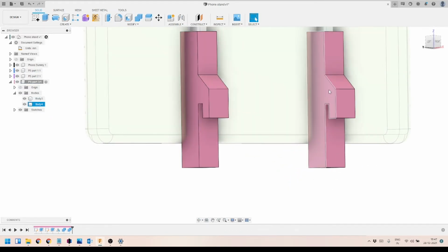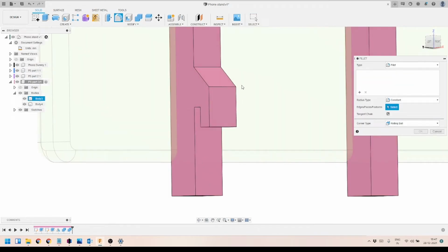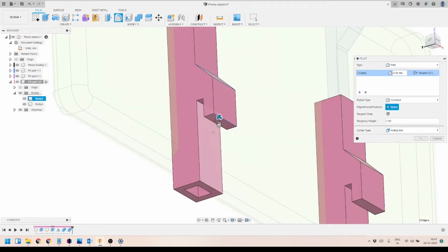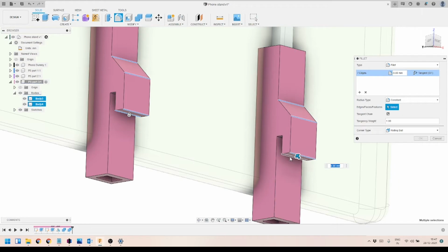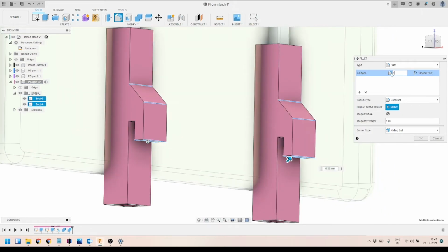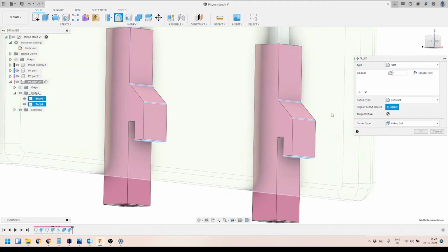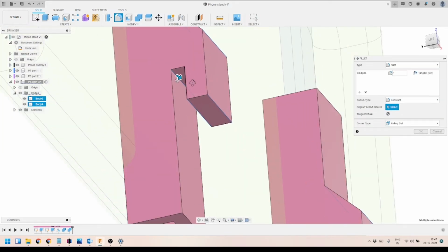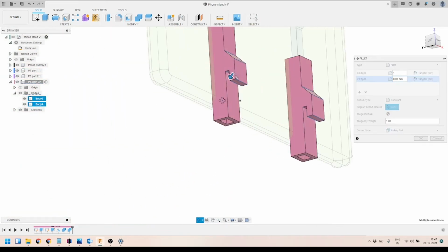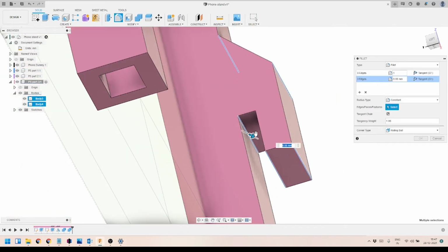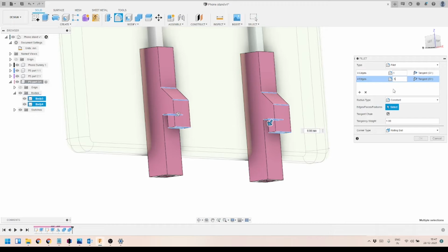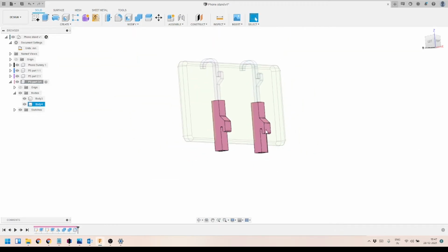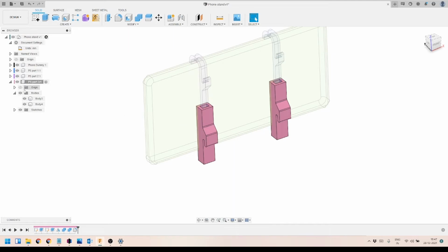The next thing is that we have to apply fillets on all the things. So I will activate the fillet tool. I will select all the necessary corners first. Here you can see I am selecting all the corners, and I will apply a fillet of 1 millimeter on these corners. Then I will click on this plus set here, and in the other set I will select the inside edges. These all four edges are just 0.5 millimeter fillets. Here you can see, and I will press OK. This is how the thing that we created looks for now.